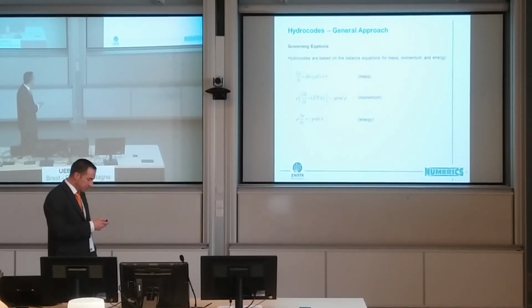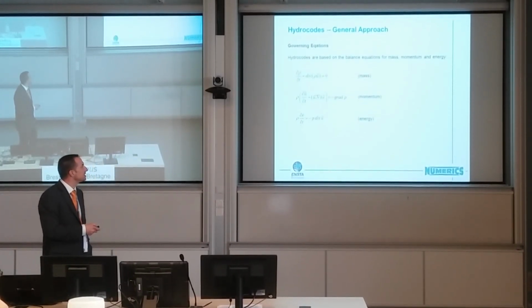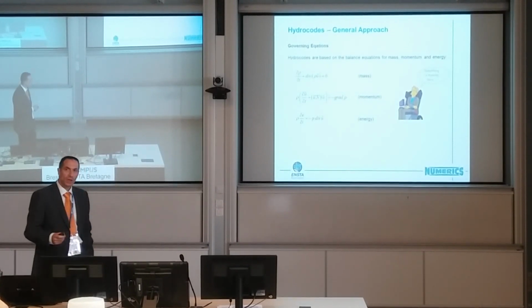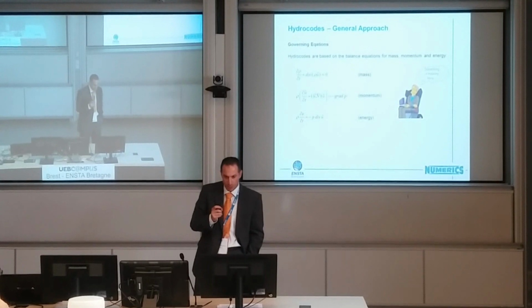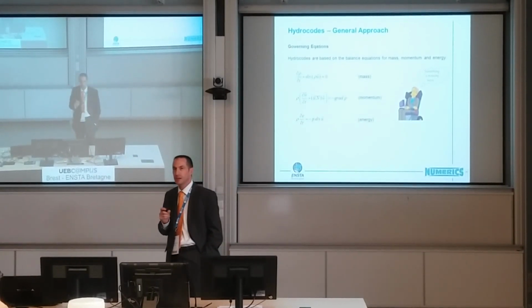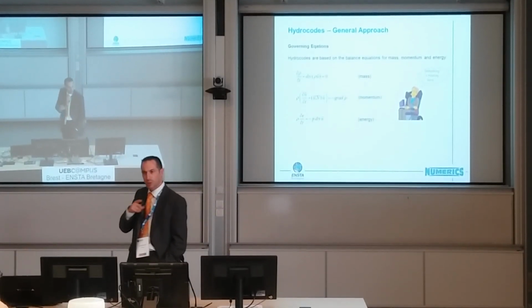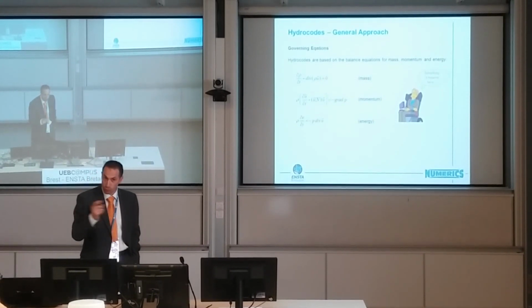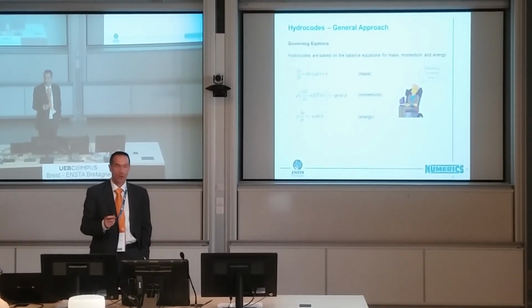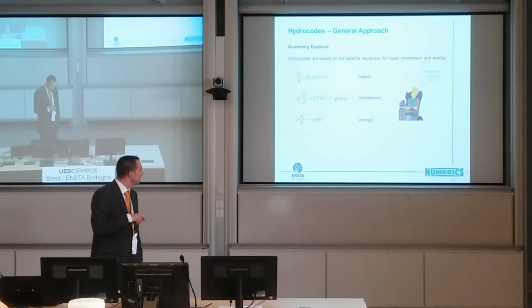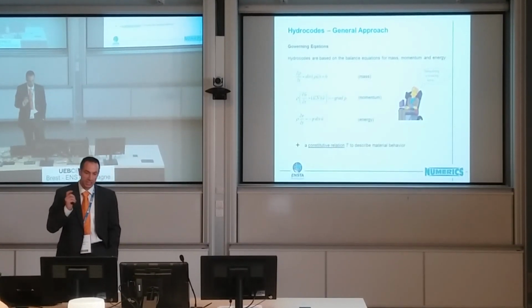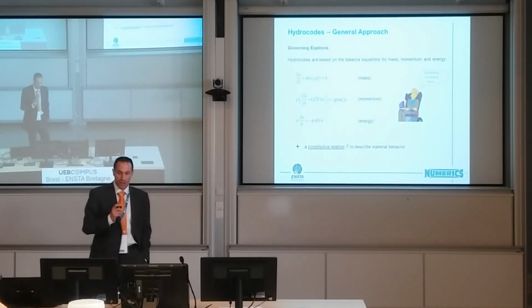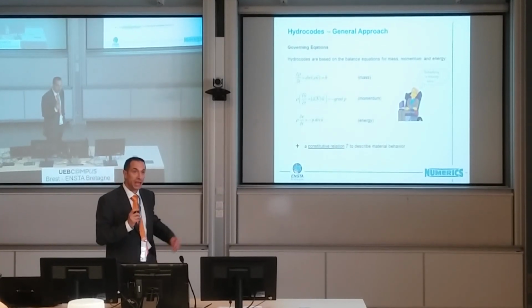However, if we have these three basic balance equations, if we want to simulate our detonation events, there's still something missing. Because with these three equations, we cannot solve the Rankine-Hugoniot equations. So what we need is an additional constitutive description or constitutive relation to describe material behavior.